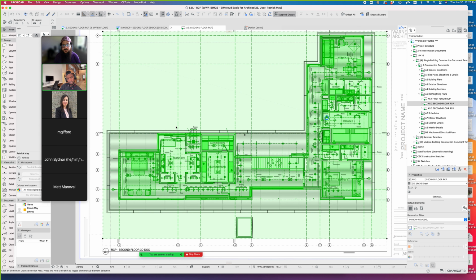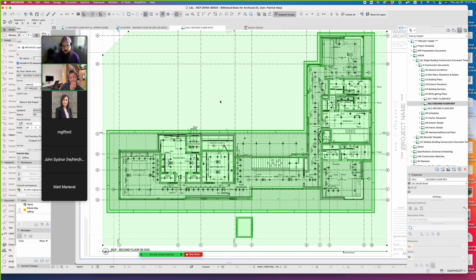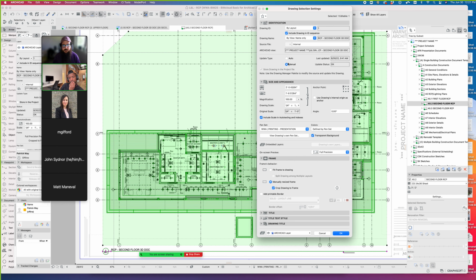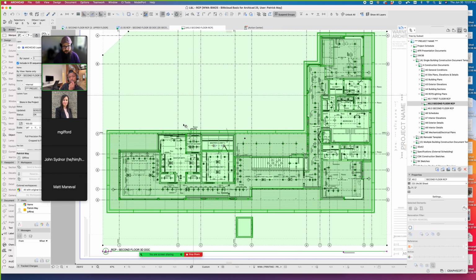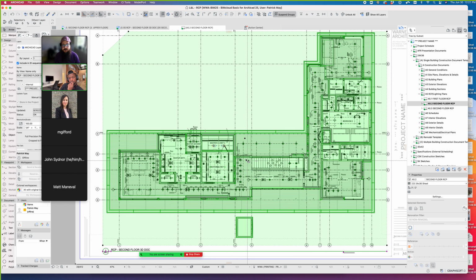A couple of other tips with that. I usually set that 3D document to manual update, and I know that there have been situations where manual update has caused some publishing issues, but you really should get a publishing warning if something is set to manual update and it's not up to date. So that 3D document being manual update can also make using this layout as a trace reference a little bit more efficient, so that as you're moving fixtures and stuff, the layout isn't trying to update in the background, which can really bog things way, way down.